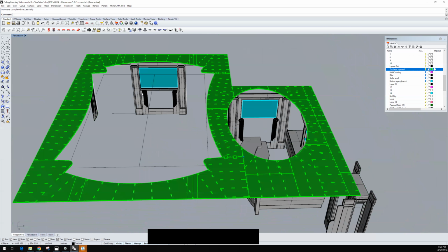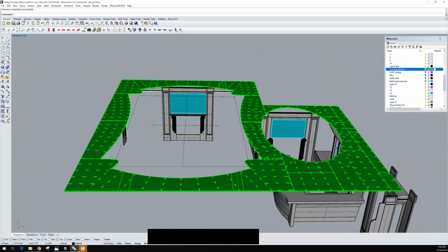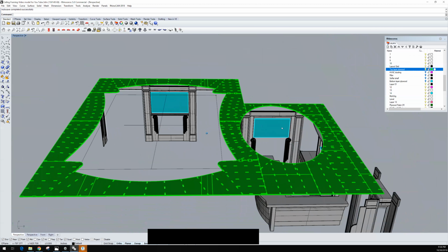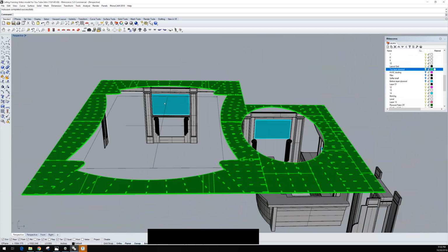One of the things that we did was, in this grid pattern here, you can see we have center of room and center of this profile. We did the same thing on this arch here, and what we did was we placed a removable temporary MDF pattern that we cut on the CNC on the ceiling that had this grid on it, which we identified with the laser.